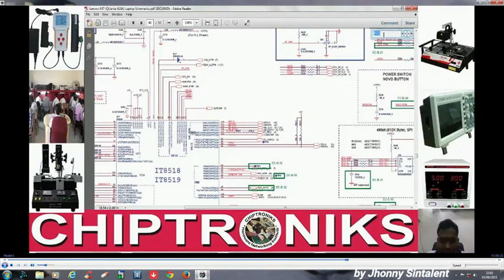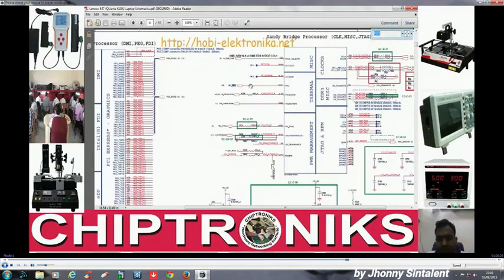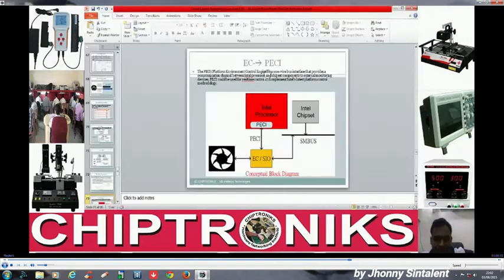You see this is going to the thermal management section inside the processor. So this is a one-wire interface to provide a communication interface between the thermal management section and the IO controller. This is a function implemented in the newest kind of Intel platforms.